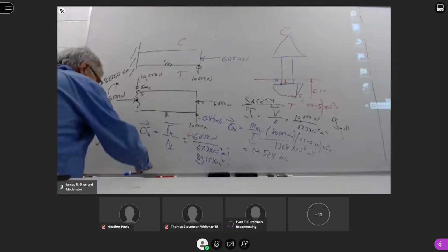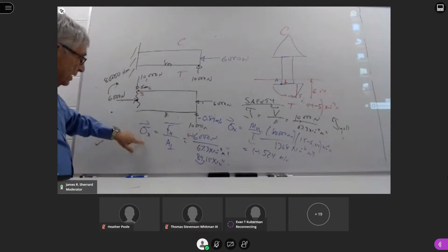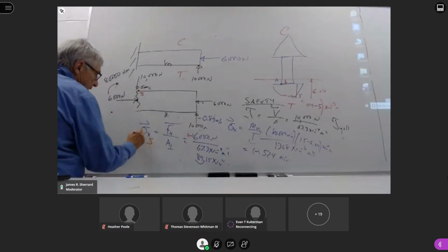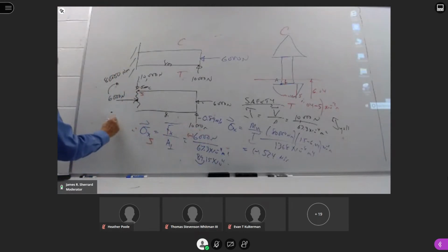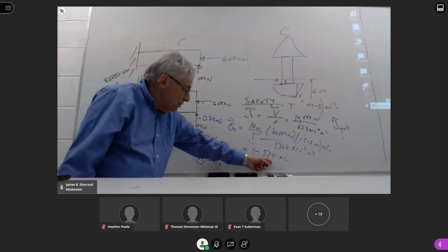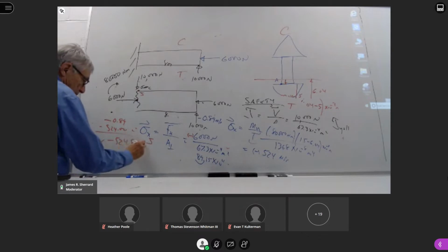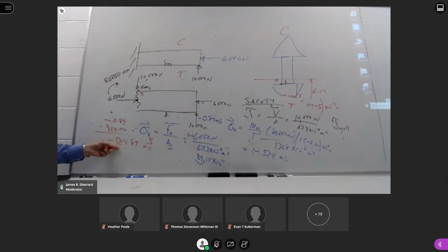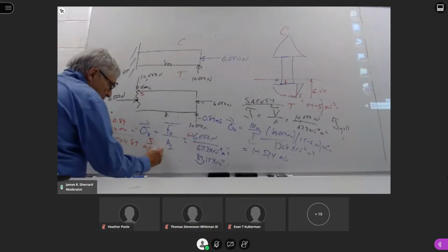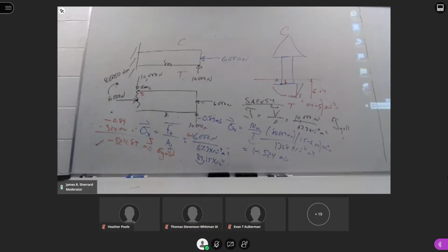So the total plane stress at point J is this plus this. This is a value that you'd compare to safety against the yield value. It failed before, and now it's even more negative, so it's going to still fail. So we could pick anywhere.